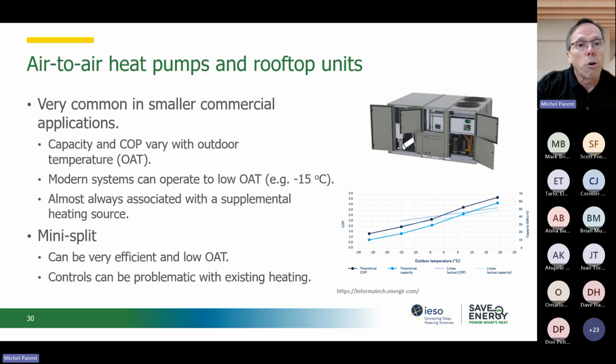Otherwise, you will be at the mercy of the OEM controller, which will not know your building demand. It will switch based on temperature, and that may not be the economic sweet spot for your building. So air source heat pumps in rooftop units are very good when they're hybrid. If you connect them to your BAS, if you have a BAS, it's obviously even better.